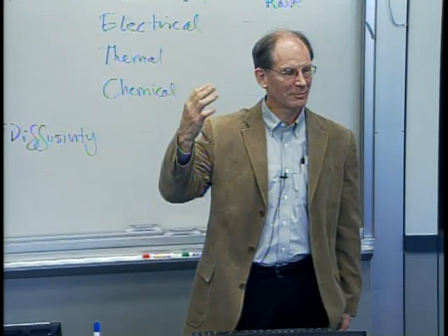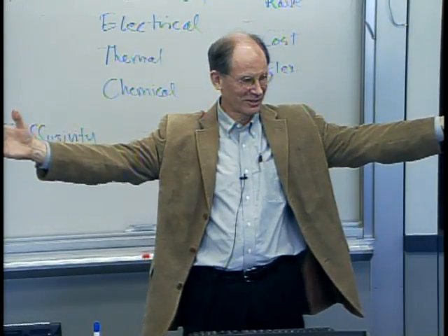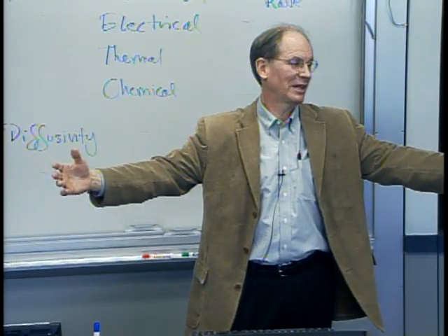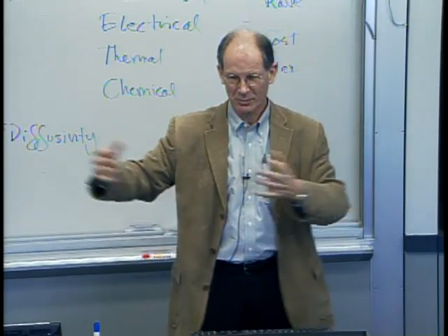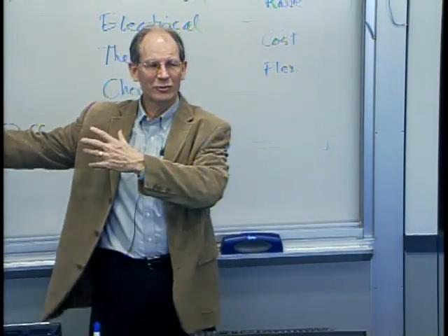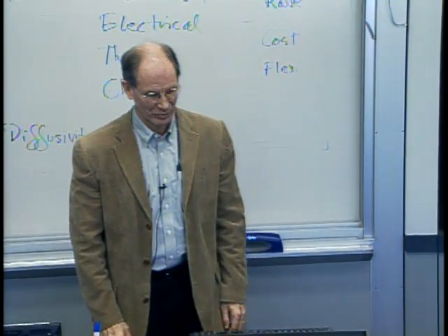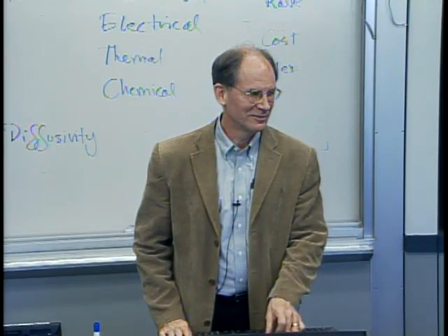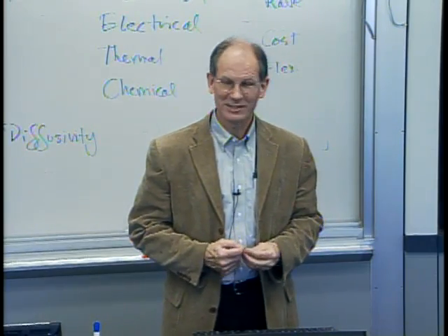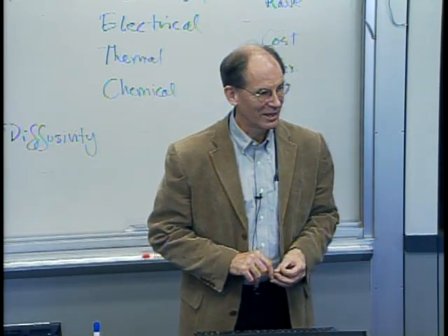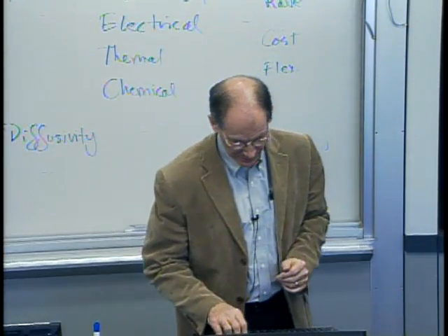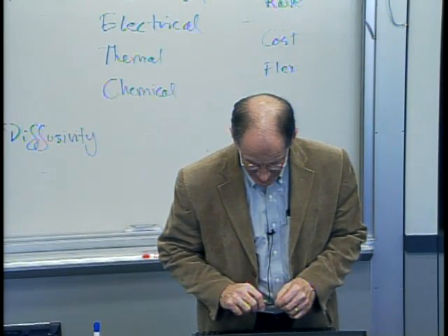Yeah. How long does it take to make a side panel for a car with integral door frames and all that other stuff? Each given operation probably takes about 2 seconds. There are multiple stages, so maybe we'll give it 10 seconds by the time it's done. But blank metal in one end and these huge complex structures coming out the other end at incredible rates. You're not going to do that with a serial process. Although I will say they've done some things with laser cutting and laser welding where that thing really whips along, but it's still got a ways to go, and it's much more costly. So all these things do matter, and they come in different ways.